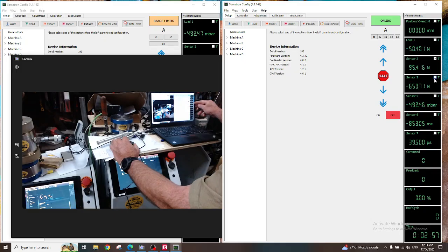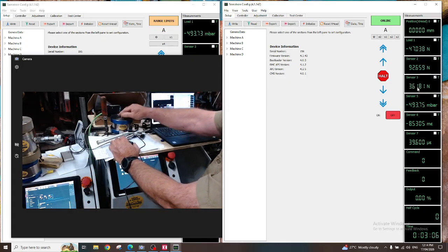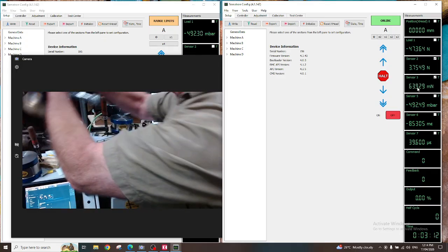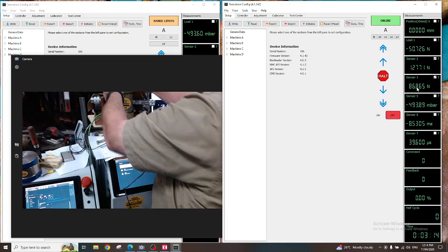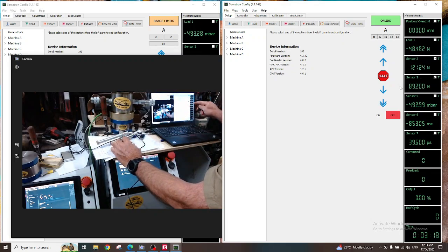The third sensor down here, sensor 3. Again, I've ticked a little tare box here. So we've got millinewtons, and that's this load cell. This is a 50 kilonewton load cell, and just to show you, I'll pick that up and put that on the 50 kilonewton load cell. You can see it's settling around the 90 newtons as well, which is about 9 kilograms.